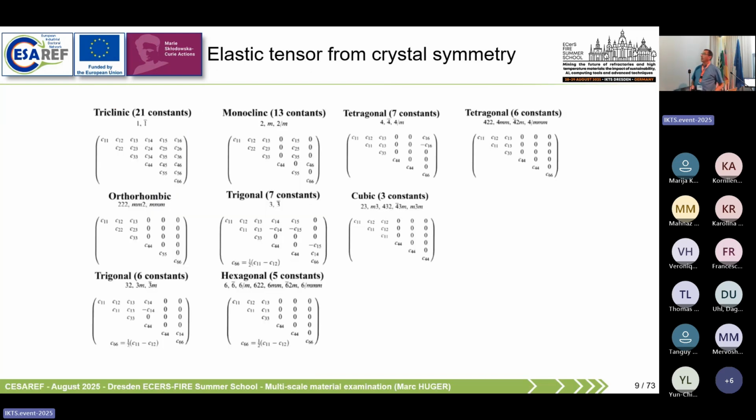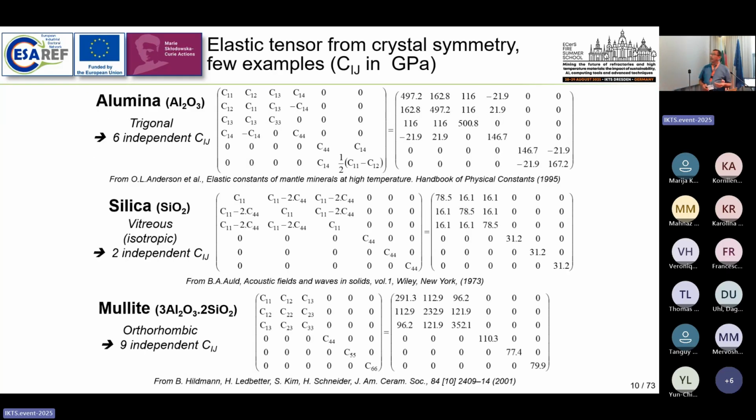So, the elastic property of a crystal is described by a tensor. You have to live with that. So, of course, the elasticity of alumina is not a simple value. You have a lot of values which describe the elasticity of alumina, due to the trigonal structure of this crystal. I just take the occasion to draw all the things that you can find from the literature for the crystal values of alumina, taking into account the trigonality.